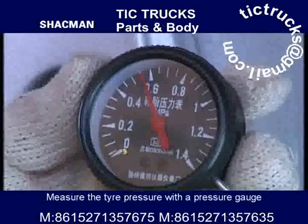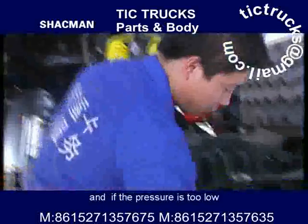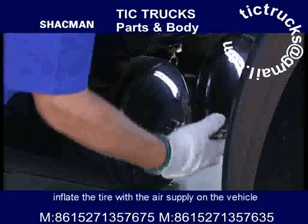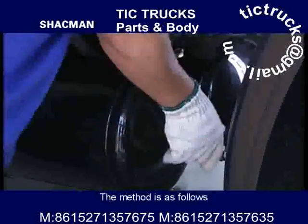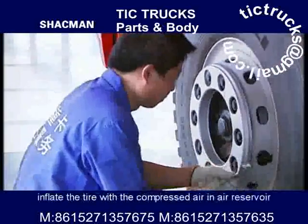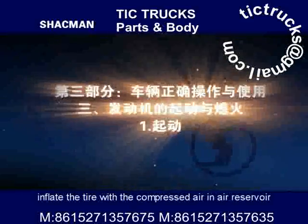Measure the tire pressure with the pressure gauge, and if the pressure is too low, inflate the tire with the air supply on the vehicle. The method is as follows. Connect the inflation hose onto the joint. Inflate the tire with the compressed air in air reservoir.